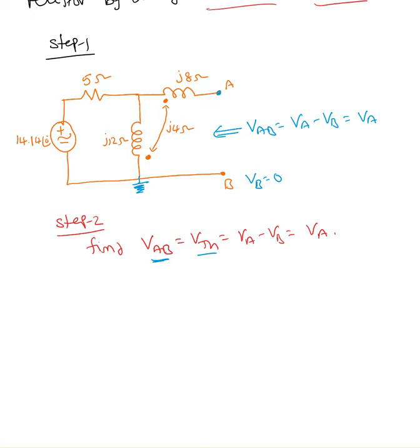So here, is there any current passing through this? There is no current passing through this because of the open terminals, but at the same time, there is some current passing through this. Let me label that as I1. So I1 current is passing through this. Because of the current flow in this L1, there is definitely an induced voltage across L2. At the same time, since there is no current across L2, there is no induced EMF across L1.